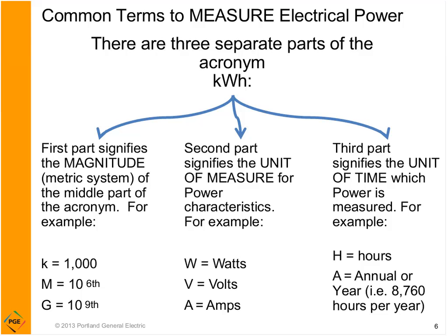Best example is if you have an office complex and you have a lot of required exit signs and you're budgeting and trying to figure out how much energy is used, you know that they have to be on 24 hours a day, 7 days a week. So you would budget 8,760 hours a year times the wattage of all those exit signs would give you the amount of energy times the price for your budgeting purposes.